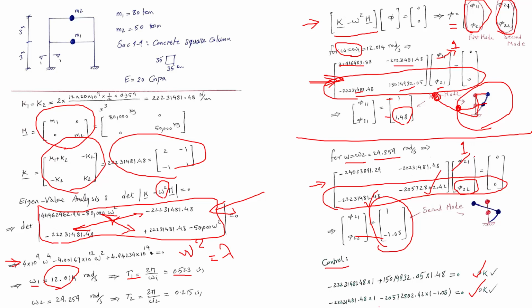These mode shapes are not the exact deformation of the structure, as I explained in the last lectures too. They form the final deformation of the structure. The final deformation is a combination of mode shapes and some other factors coming from external forces. The mode shapes depend only on stiffness and mass, so they come from the nature of the structure, not from external loading.